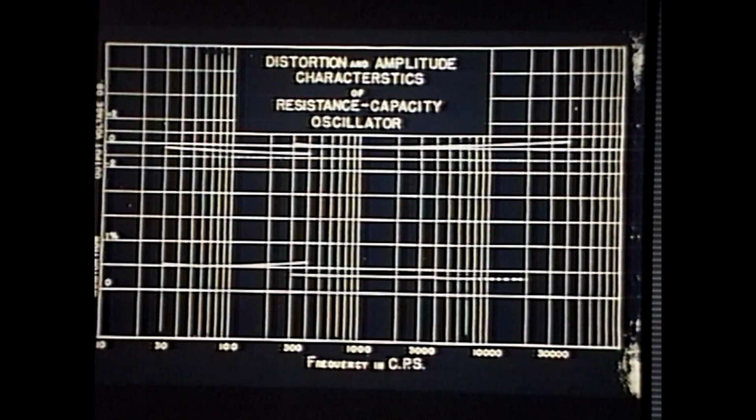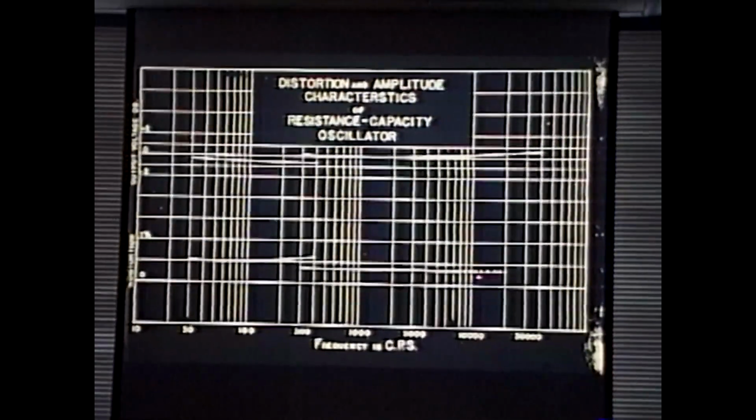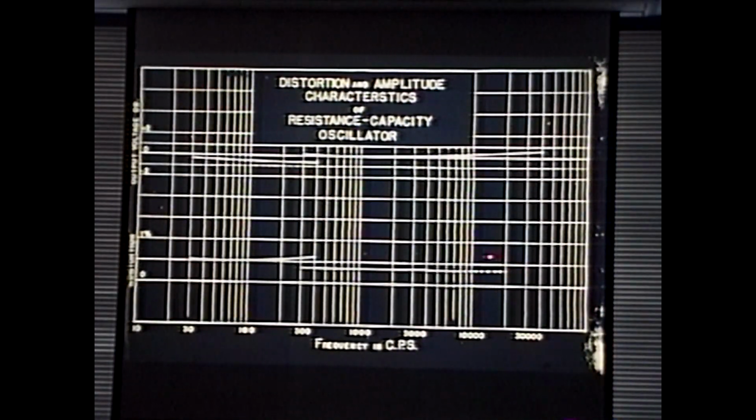What did he get? Well, look at his distortion figures here. Not bad. From about 30 hertz out to about 10 kilohertz. This isn't his oscillator circuit running out of gas, it's his instrument running out of gas, his ability to read. Out to about 10 kilohertz, he's well inside 0.5% delta on distortion. And amplitude flatness isn't too bad either. He's well inside a dB or so.